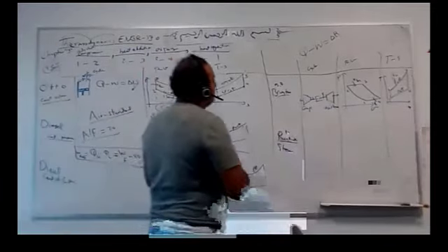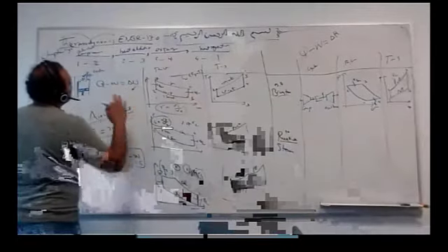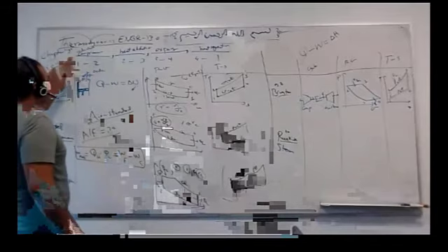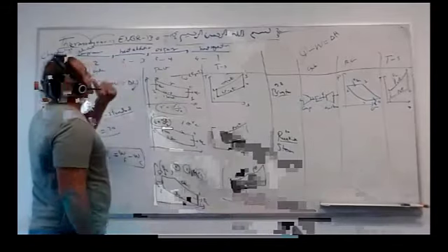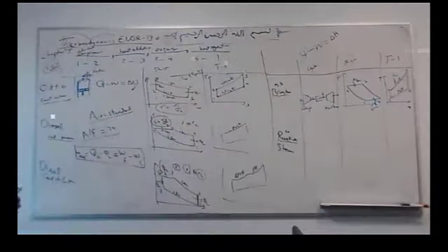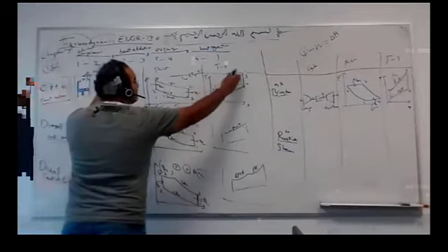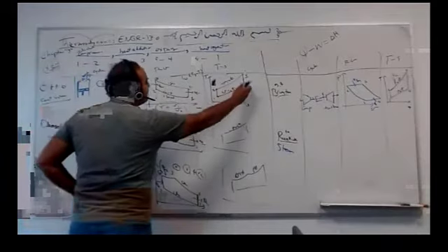So either you have Q or W. Usually Q does not exist in compression and expansion because it's adiabatic. Always isentropic because it's reversible, adiabatic. But heat addition, it's called heat addition, of course it has entropy. And usually, if you have addition, entropy increases. Heat rejection, entropy decreases, and so on. This is the thermodynamics definition or basics. So heat addition and rejection, of course, are not isentropic.